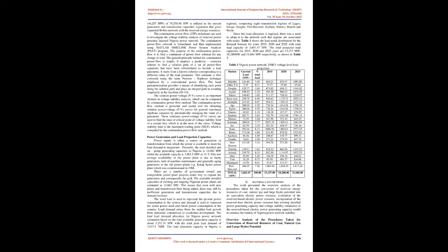Introduction. The existing Nigeria power network, which comprises 5,988 km grid transmission lines, 330 kV, is faced with the following problems: inability to effectively dispatch generated energy to meet the load demand, large number of uncompleted transmission line projects, reinforcement expansion projects in the power industry, poor voltage profile at the bus, inability of the existing transmission lines to wheel more than 4,000 MW of power at present, operational problems, voltage and frequency controls.